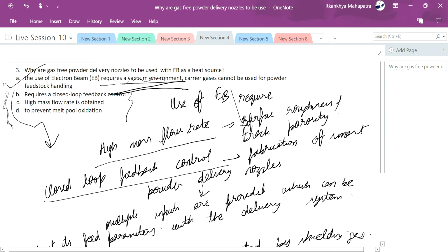So with this we also discussed some of the prime features of the powder delivery system. Apart from this, we also have the smart powder delivery nozzles, omnidirectionality, which we already discussed, and proper feedstock material selection, such as aluminium and copper, and stream characteristics. Particle velocity should be low for increased catchment efficiency, and the powder injection angle should be low to support a longer depth of focus, to promote high deposition efficiency. These are the primary features of the powder delivery system in powder feed based additive manufacturing.